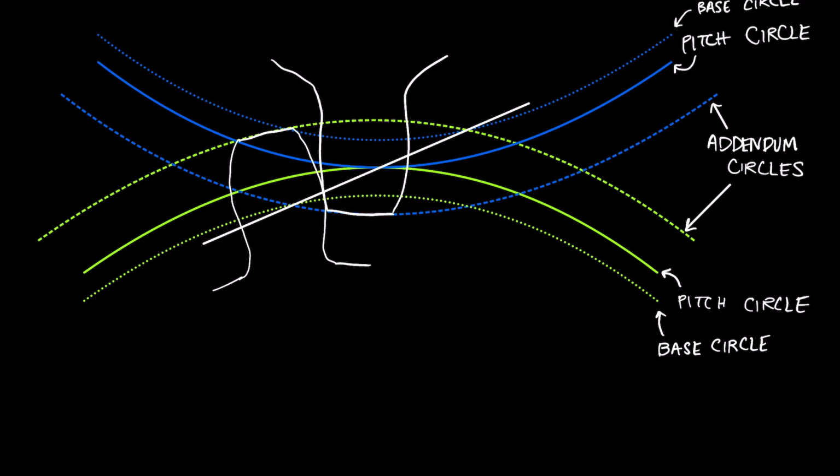Okay, I think this is as good as we're gonna get. So here I've drawn two gear teeth which are coming into contact with one another. I've labeled those points A and B once again on the pressure line so that we can see where this contact is actually occurring, up here. We'll call this point C. And the reason for that is because these tooth profiles are not exactly conjugate.